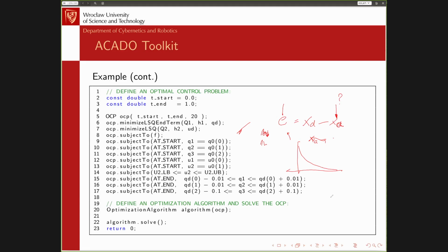So you measure something else, like you measure acceleration, and based on the acceleration, you can estimate the position and velocities. Or you measure some velocities and you estimate position. Or you have different sensors, like laser scanners, and you can measure distances to some known objects, and based on that you can do triangulation or trilateration, and measure your position with respect to those objects. So there are many methods.